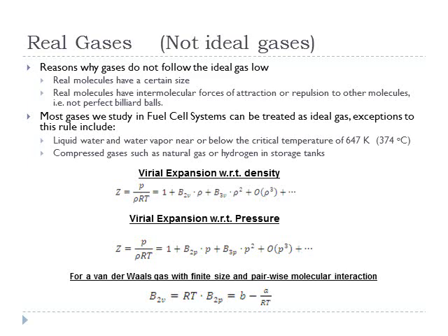So the next thing we're going to look at is hydrogen. You can see hydrogen, as long as you're not anywhere near cryogenic temperatures, you can almost treat it as an ideal gas, though its critical pressure is not too high. So when you start storing it, you can hit cases where you may be storing it at maybe 120 atmospheres or something like that. So you're actually sitting at very high pressures compared to its critical pressure, and there's some small non-ideal effects that come into play.